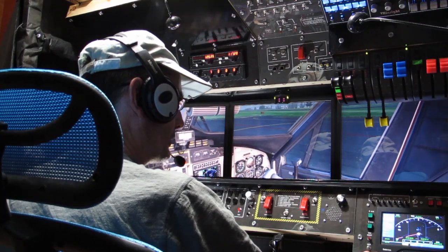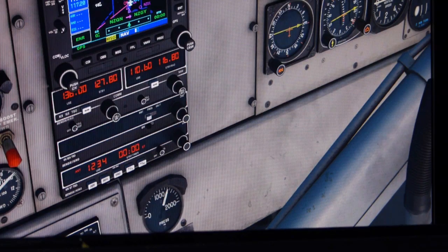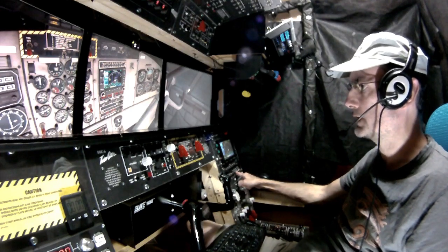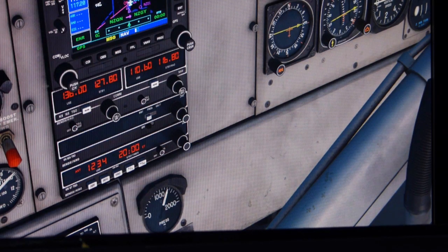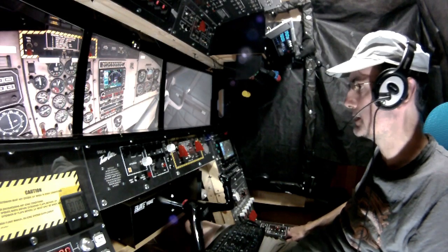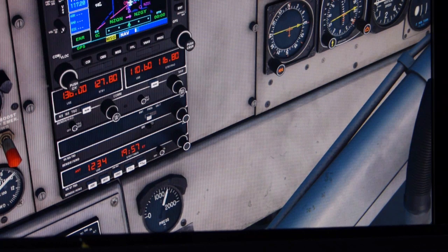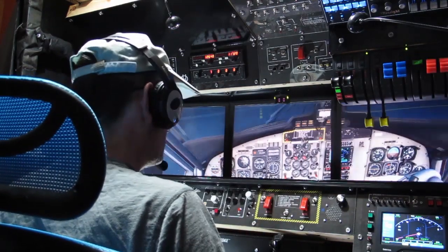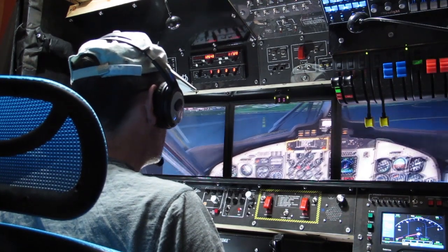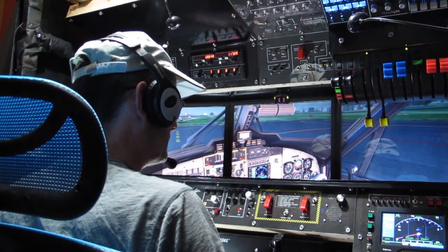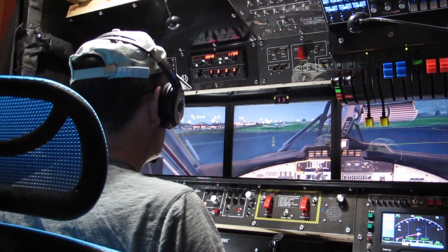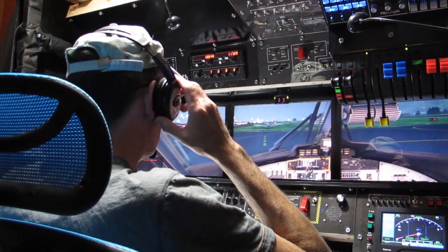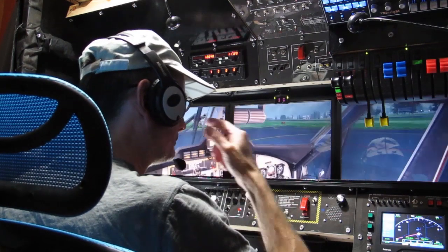Before I do that, I'm going to do one more thing which I've just remembered. I'm going to switch on the ADF radio as well. I'm going to press the flight elapsed time button. I'm going to press it again so we're on elapsed time. I'm going to hold the reset button down for 2 seconds, and so we're into setting the countdown timer. Actually I already had it set from before, so I've set it for 20 minutes and I'm going to let it run. The reason for that is it's going to beep when 20 minutes expires. That's just a reminder for me, because my cameras are going to stop recording after about 25 or 30 minutes, so I don't want to get caught out by that again.